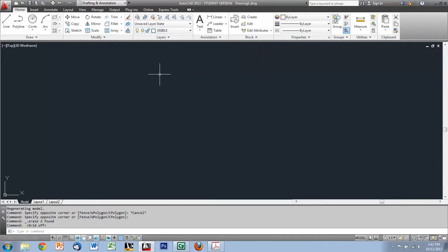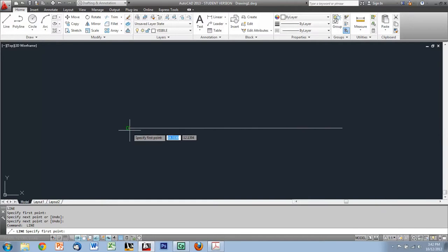One other thing that I'm going to set is my O-snap settings. And the O-snap is right down here. Whenever you see a line, for instance if I'm going to draw a new line and I hover over the end of this, you'll see where I get these little boxes or triangles pop up. That's your O-snap, and that's letting me know, for instance, that if I was to draw a line with the end point beginning right here, they would be perfectly touching end to end.